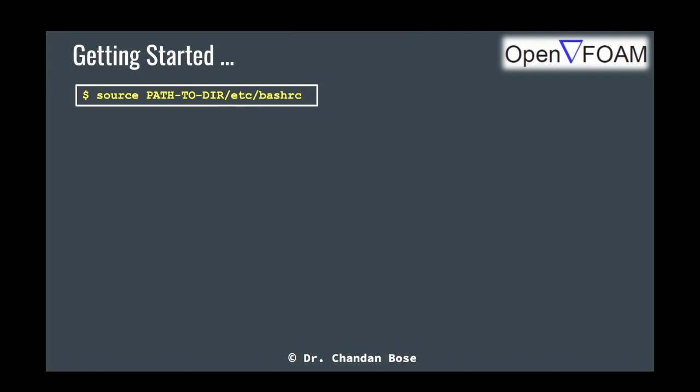And if you are aware, any operating system you are using also has a default bashrc file, which is called the system bashrc, where even unknowingly you are using some control settings which dictate what your programming environment will be when you switch on your operating system. All right. So this is the same for OpenFOAM. And once you source this, you will be able to see that your OpenFOAM functions are recognizable by the terminal, and it can link all the libraries and their locations. Once I get the terminal ready, I will show you all this.